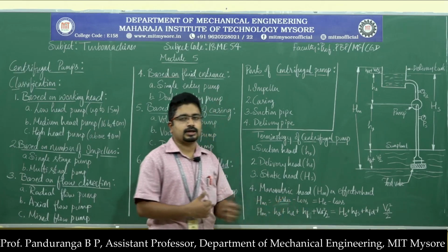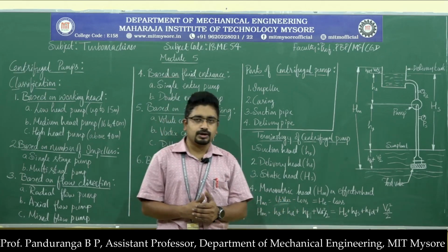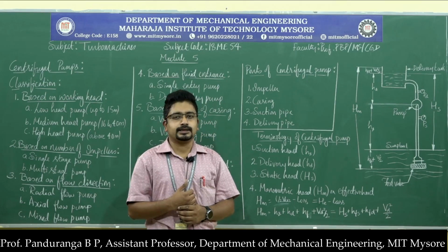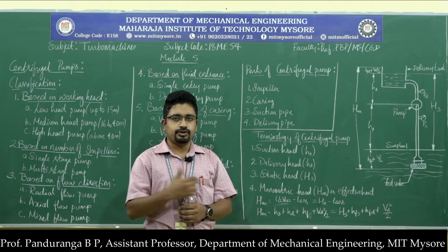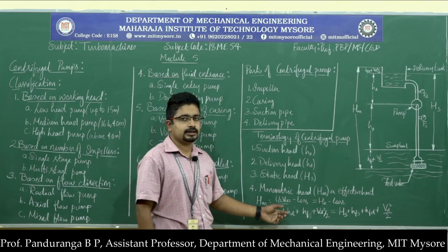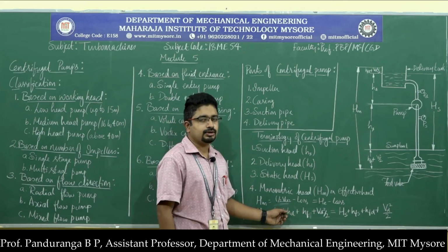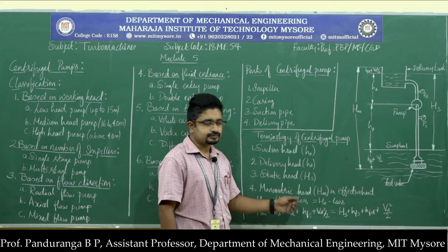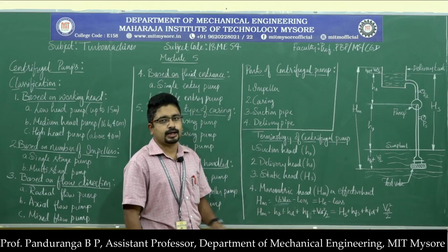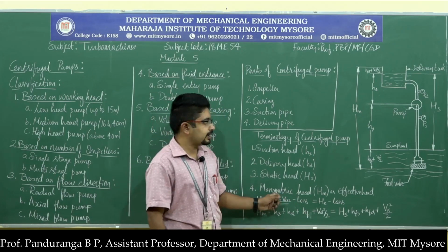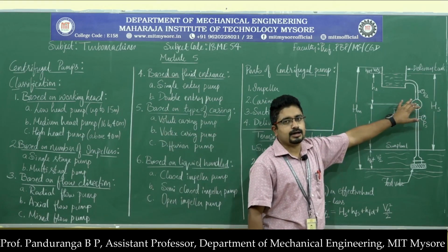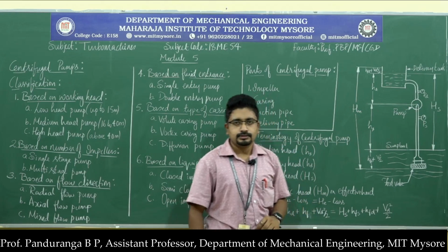We are not considering U1 VU1 because VU1 will be 0, since the fluid is entering in the axial direction. Energy transferred in the pump will be equal to U2 VU2. So U2 VU2 minus losses will give us the manometric head, which is not considering the losses that occur near the impeller and casing.